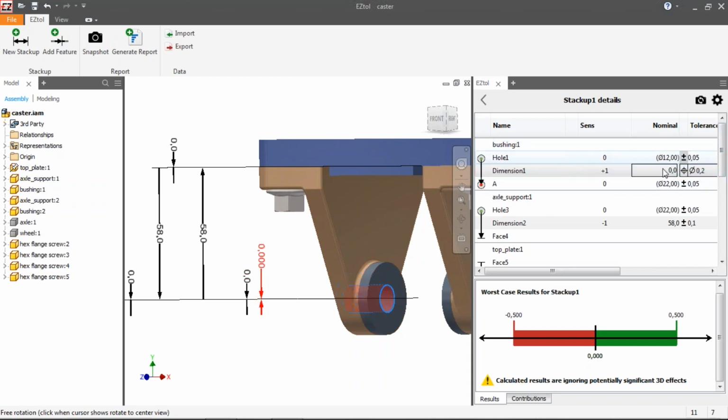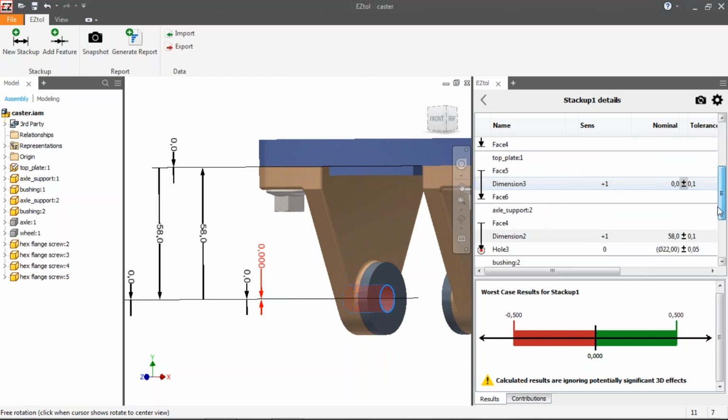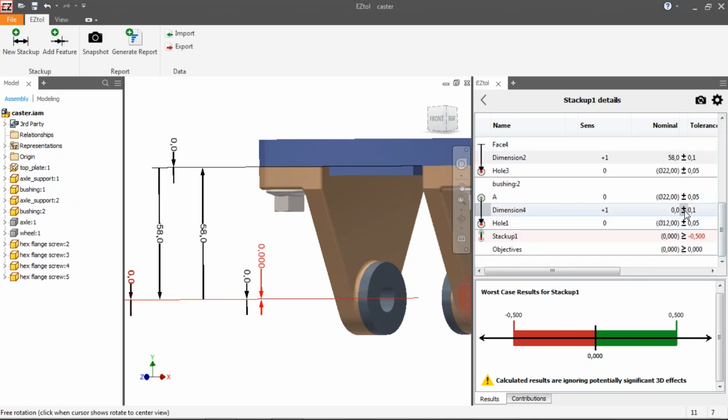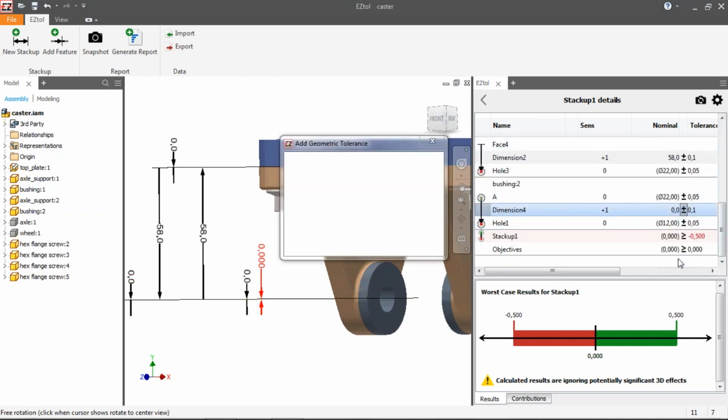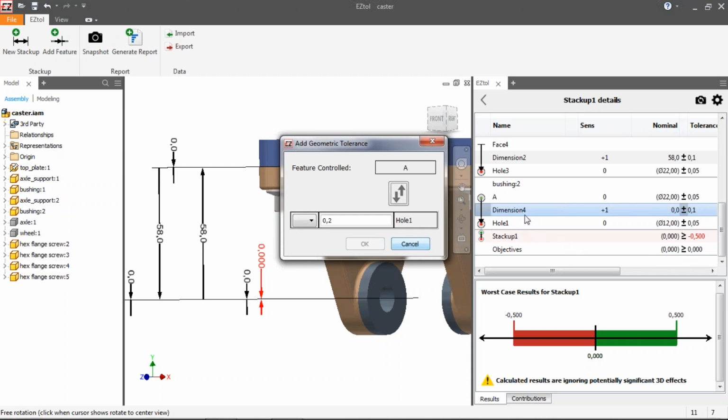So we have our geometric tolerance here on one side. Just go down here, also select it on the other side. And since on this side datum A is the incoming feature, we can swap it around here, so we have it as our datum.